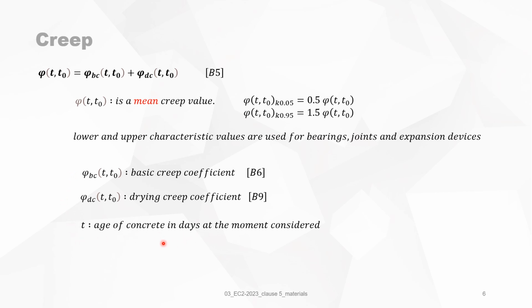t is, of course, the age of concrete in days at the moment considered, and t0 is the age of concrete at loading in days, adjusted according to B17.